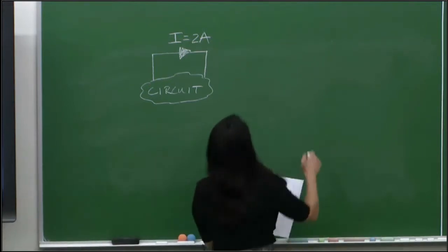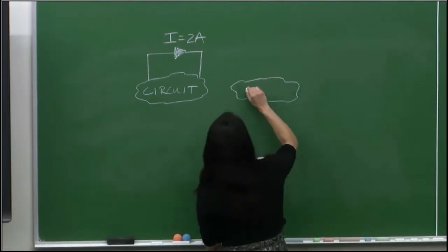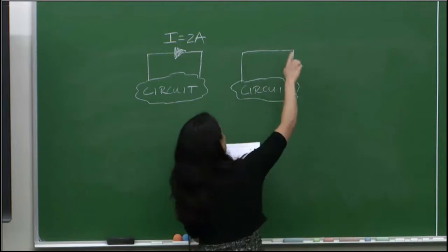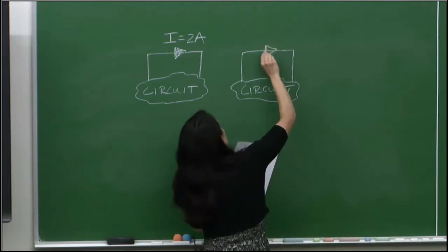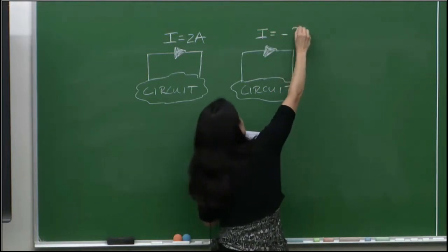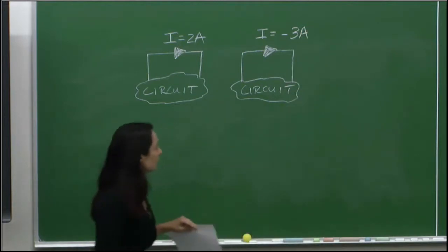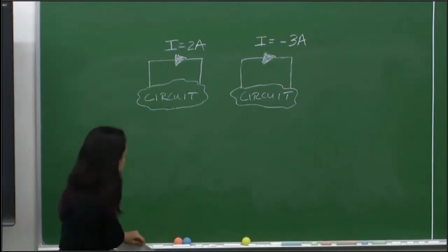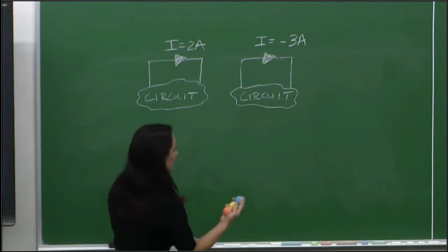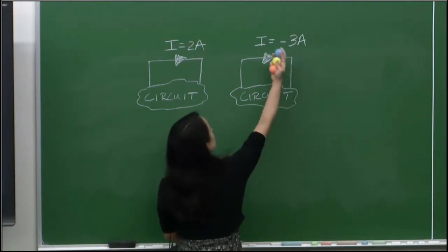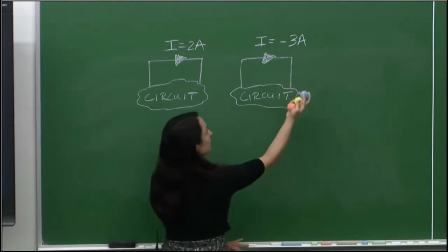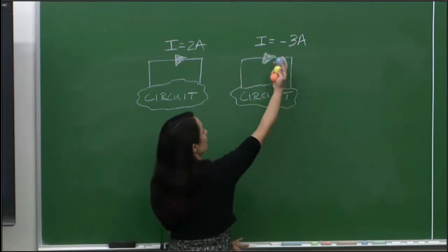If you start seeing things that have a negative current number, so we have our mystery potato circuit, we've cut a piece of wire, or we have a piece of wire coming off across there. We're going to assume there's some current flow. But when we put our meter on there, it reads -3 amps. If you get a negative reading when you're doing something like that, it means the current was actually flowing the other way. So at any given second, you have 3 coulombs going from right to left across there. Even though this arrow is drawn, we were just assuming a direction. When you get an actual readout, if it's negative, it really means the current was flowing the other way.